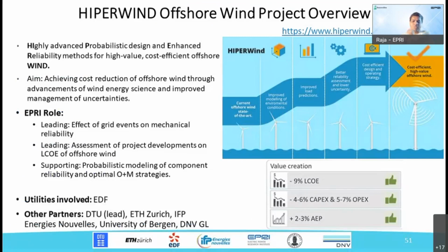and then transmit those loads onto the main rotor, and then convert those loads into stresses on the individual components along the drivetrain, like gearbox bearings, main bearing, and generators. And once you have these local loads and stresses, how you can use them to predict the reliability of the critical systems and components.